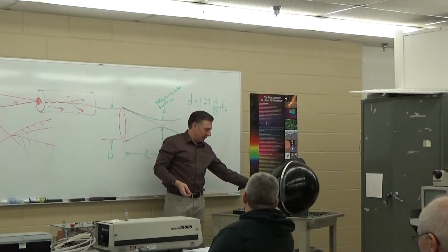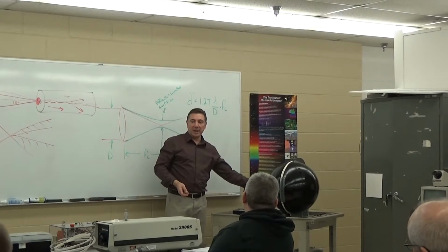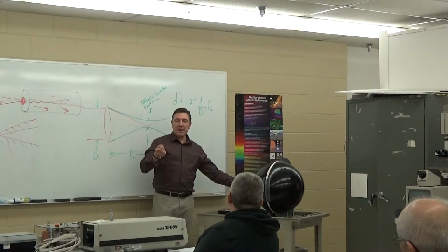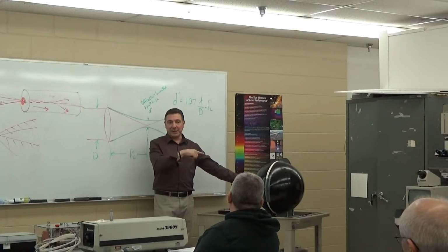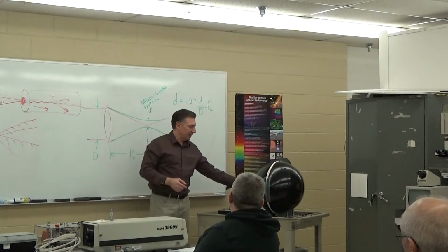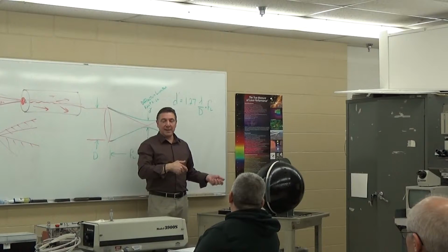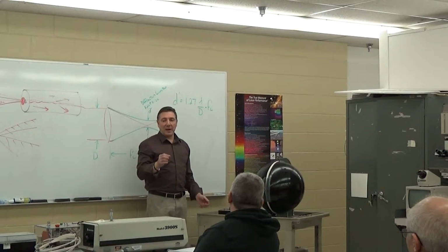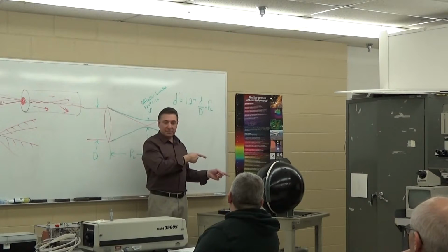On the side there's a slot, a hole for a fiber optic probe that picks up the amount of light. If you have a calibrated bulb from the National Institute of Standards, put it in there. You know this is how much light a 100-watt bulb puts out. Measure that, take it out, and put your bulb in and measure it. You can get an exact measurement of how much light is actually being given off by the light bulb.